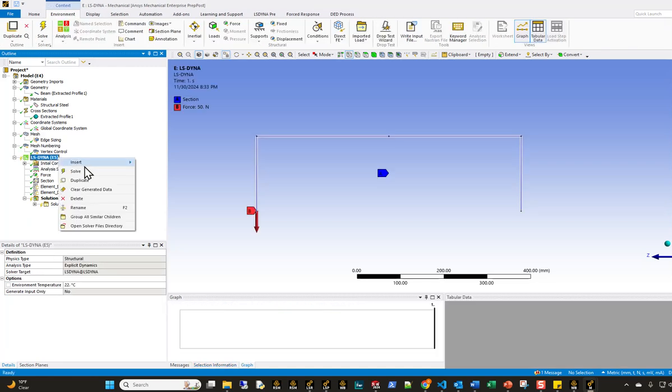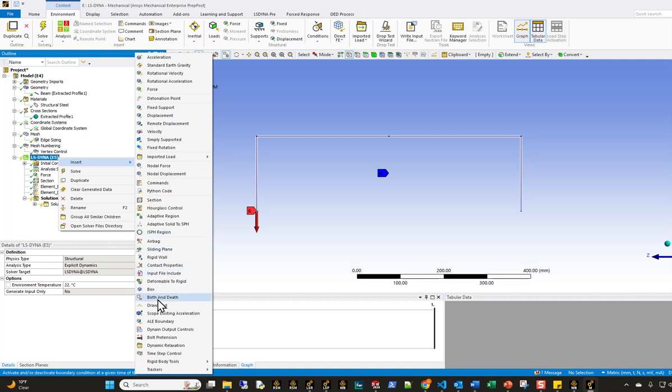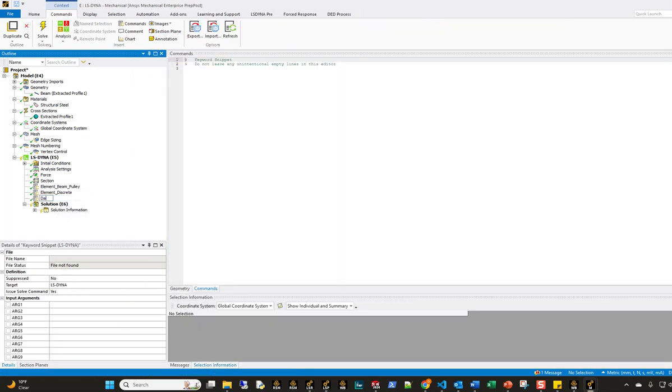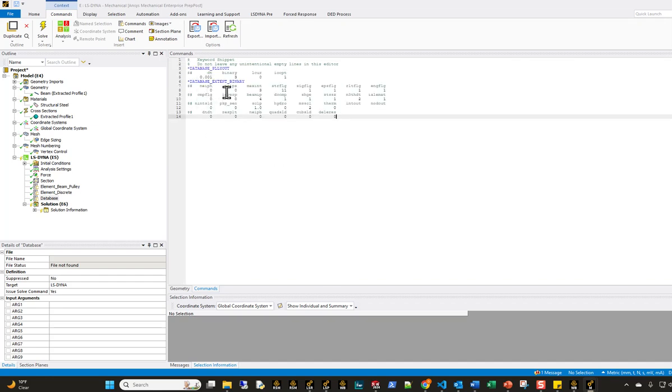And the very last thing I'm going to do here is create a database card, as I always do. The database card is going to allow me to probe some additional information related to the pulley and related to the beams, right? So I have an element pulley out, database pulley out, which is going to collect some information about the pulley, just because we're doing a pulley analysis.